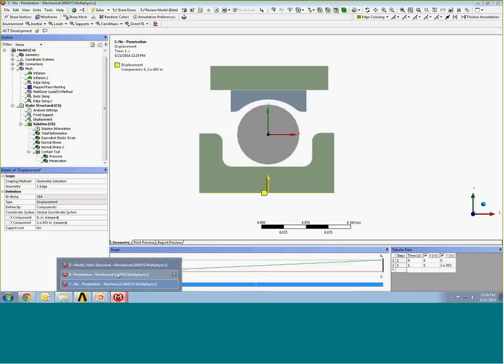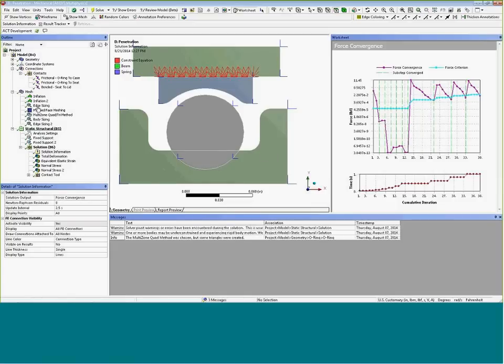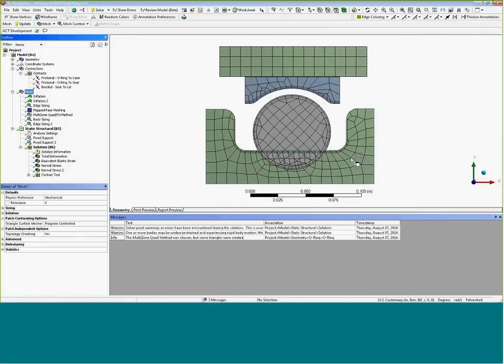You would have to model it this way, where the shaft is the right diameter, the bearing's at its right diameter, and then you can have some interference fit in there and then just resolve it out, based on the contact. And there's some other ways you could probably do this, but just showing that in this case, this would be an easy way if these were an axisymmetric model to preload this gasket in there.